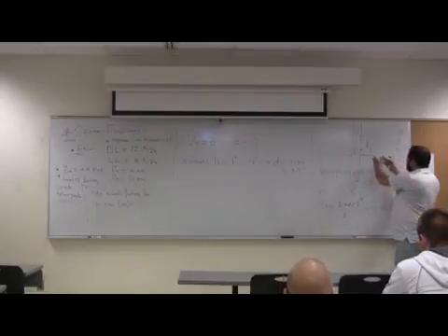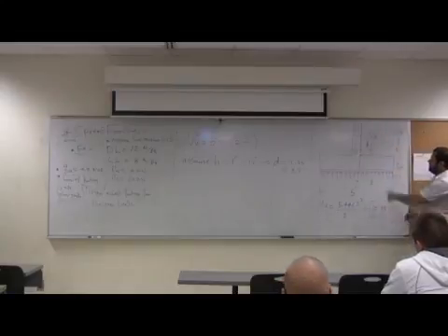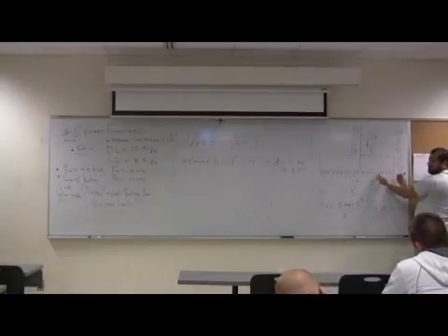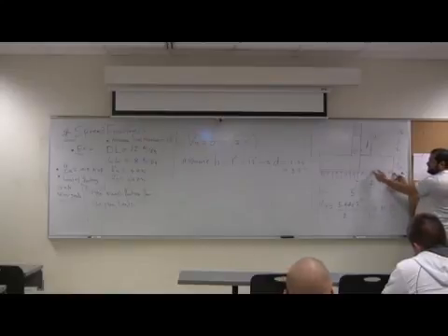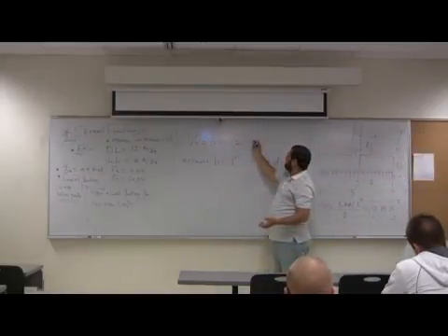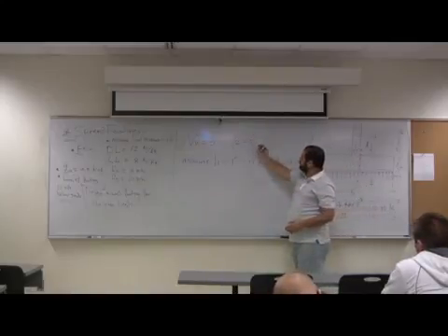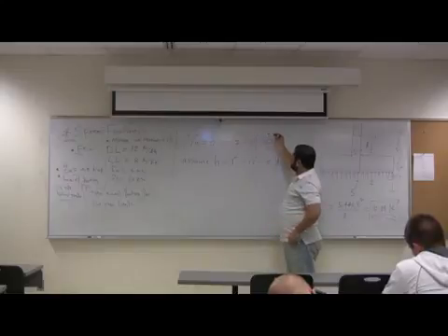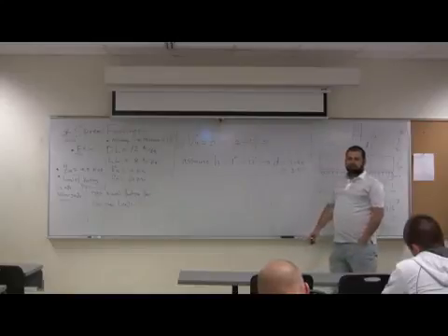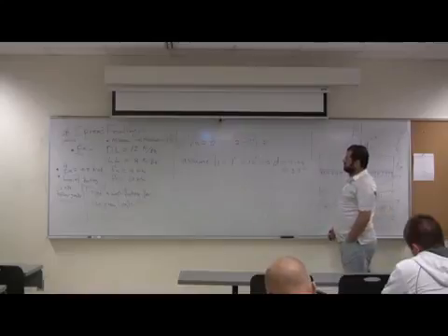In this case, what's the V value here, or V ultimate here? This one will be Q ultimate. If I take a cut here, Q ultimate times this length, which is 2 minus that. So Q ultimate times (2 minus 8.5 over 12). You change it to feet. This will give you how much? Eight and a half divided by 12, subtracted from 2, times 5.44.